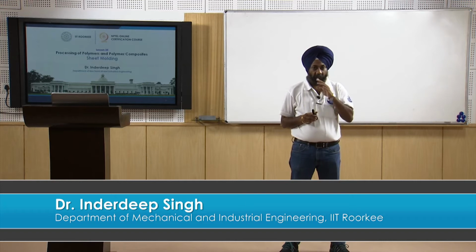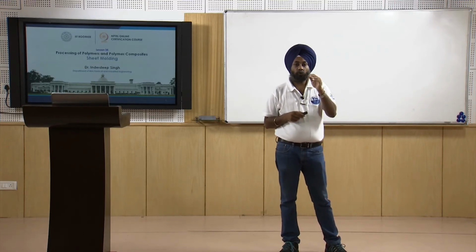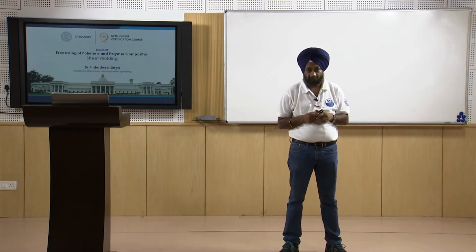Just to have a review of what we have covered in the previous sessions, we are currently focusing our attention on polymer composites and the various processing techniques that are used for processing of polymer based composites. We have seen that the major classification can be based on the mold, and we can have open mold processes and closed mold processes. And if you remember, just to revise once again, in closed mold we have seen compression molding, injection molding. In open mold we have seen hand layup, spray layup processes.